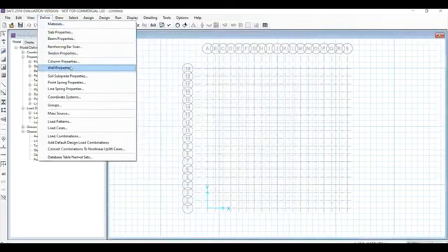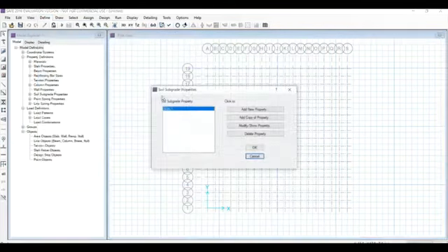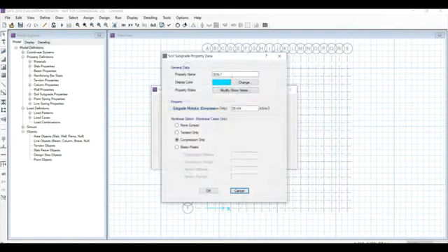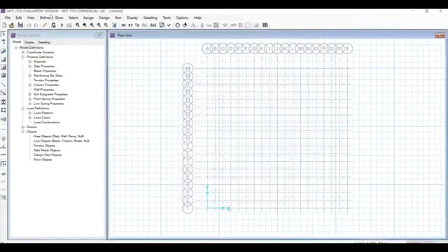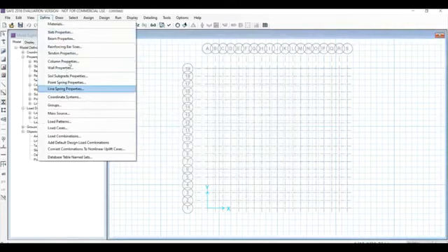And now define the soil subgrade properties. Let us assume about 30,000 for soil subgrade properties, and modify the soil subgrade property. And here we have 20,000. So make it 30,000 by changing here to 3, and then click OK. Click OK, and then the column properties are completed and the soil subgrade properties are also completed.